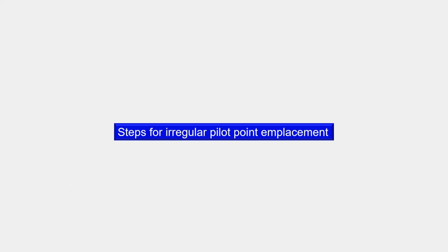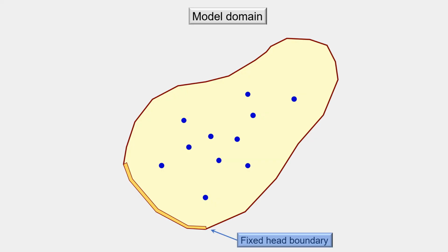So this is the line of thinking that I normally employ when I'm emplacing pilot points in one layer of a model domain. The same logic can apply to multi-layer models. Just apply that logic within each layer of a multi-layer model.